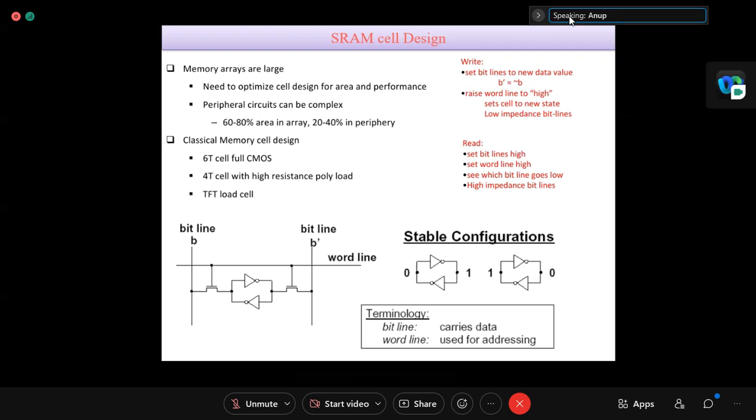So below you have one switch, a two-way switch, and on top you have another switch, and those switches are connected in XOR format. One has to be 1, another has to be 0, then only the light will be on. So these kinds of gate operations we are using in our daily life.